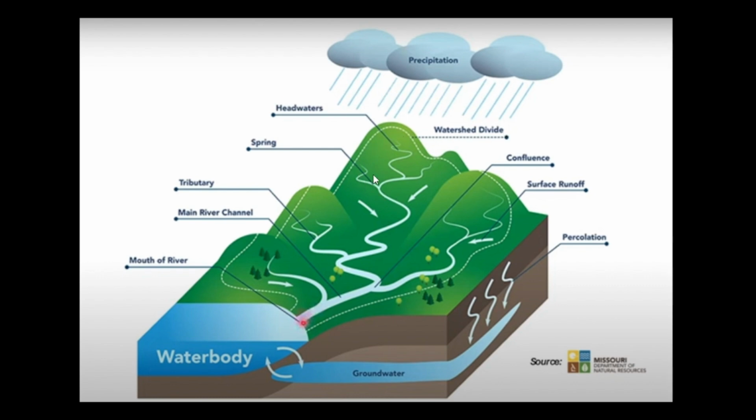And here are sub-watersheds or sub-catchments. I can check this one this way. If I want to use this part only, I can make the watershed boundary here. And here is the idea of defining a watershed. The watershed or the catchment is an area of land that drains water into a specific location or point.